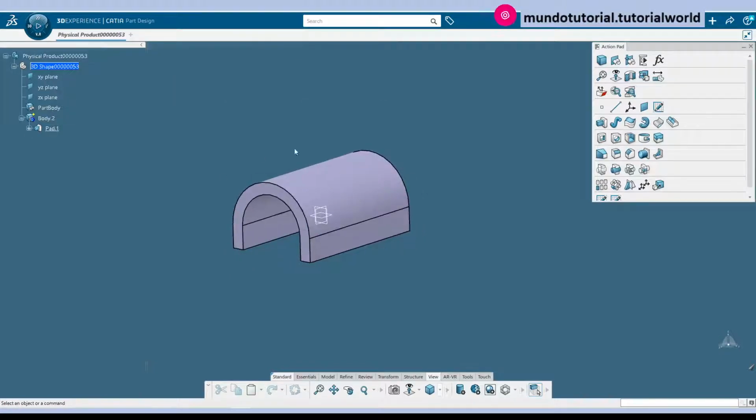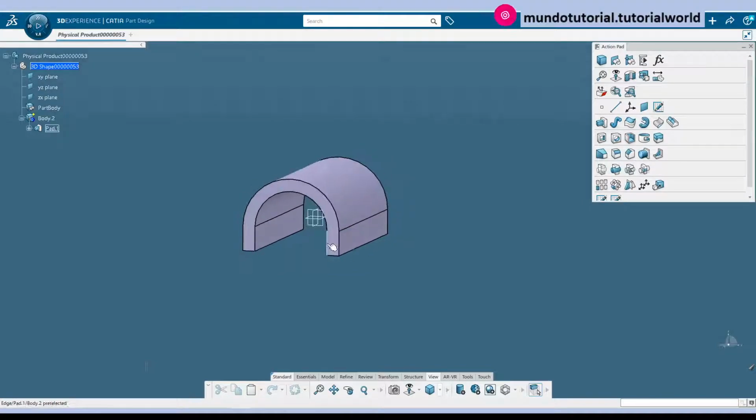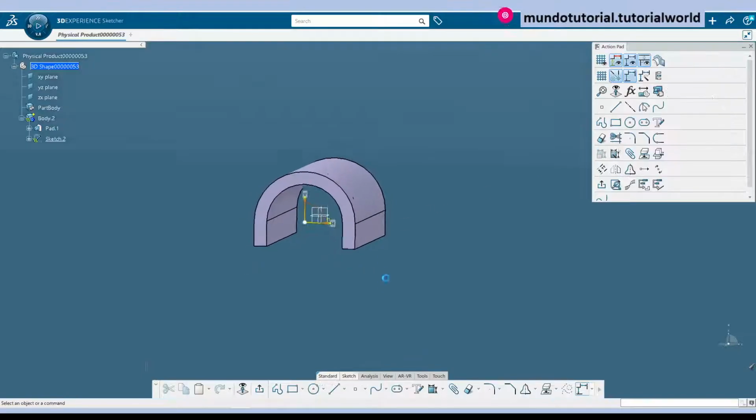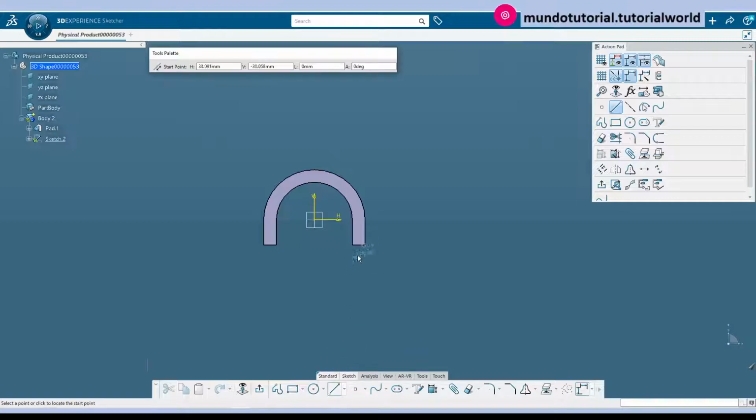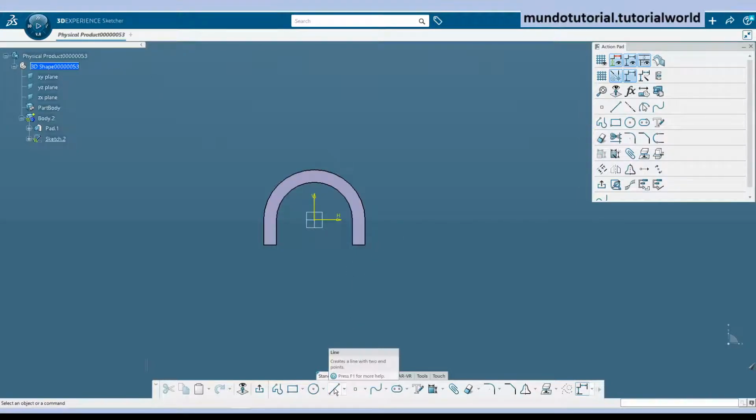So now let's finish this geometry. We have the main bridge, and now let's add the extra flange that we have on both sides where we will add the hole. What we will do is add just the flange on one side, add the holes, and then create a symmetry. So if I take this as support here, we can follow the same strategy. Just create a line, make it coincident there.